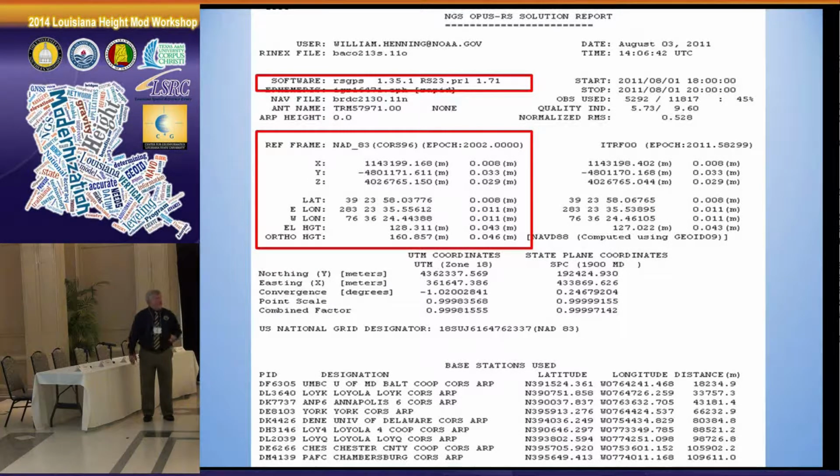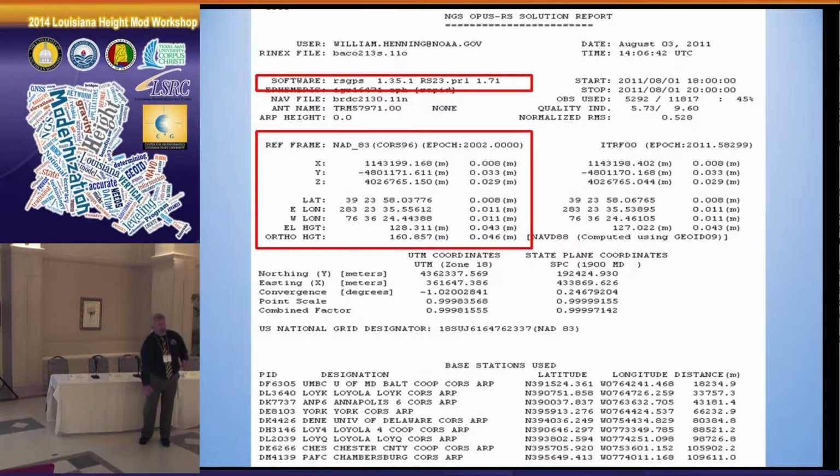Of course, that's very important. If you give it the wrong antenna name, you're not going to get a good elevation back, I can guarantee you. So you make sure that it's one of the NGS antennas that's been modeled, which they've modeled almost all of them, and make sure you're using the right one. This is going to return the antenna reference point because the height is 0, 0. If you had a mark and you were set up over the mark, you'd enter the height, the HI, to the antenna reference point of your antenna.